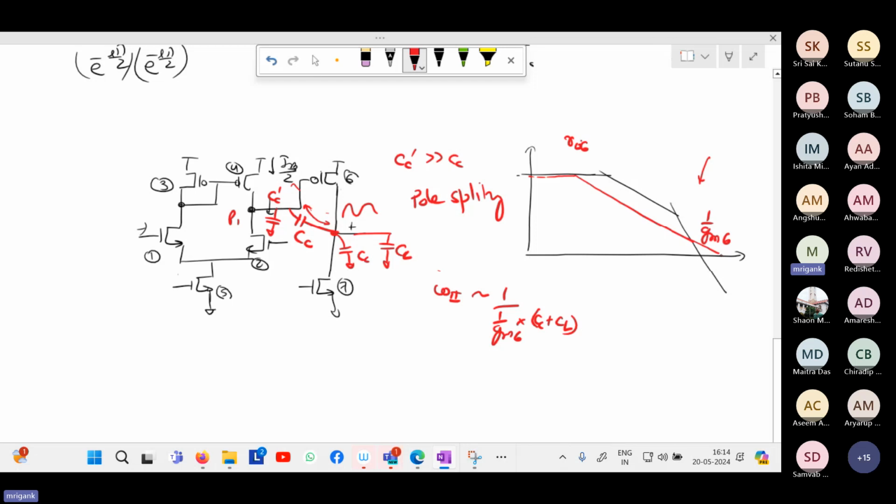And the ideal case is that the shift is such that the crossover point or the second pole comes beyond the zero crossing or at the zero crossing. So here what I've done is I've shifted the two poles. P1 became lower, this P1 dash, and P2 dash I shifted to this point. After P2 dash, there is a minus 40 dB per decade. Now, if I have made the P2 equal to omega 0 dB, that means the P2 is coming at or after omega 0 dB. That means zero crossing point, the crossover frequency at which the gain becomes 0 dB.